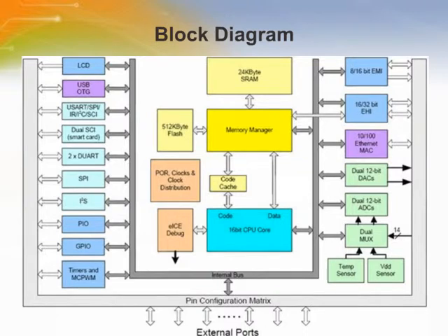Here is the block diagram of the eCOG1X microcontroller. The eCOG1X flash-based microcontroller contains a 16-bit RISC processor with powerful mathematical instructions. There are 512 kilobytes, which is 256K by 16-bit data words, of embedded flash memory, and 24 kilobytes, which is 12K by 16 bits, of internal RAM available on chip, which can be used for both code and data storage. The internal memory manager maps both internal and external physical memories into the code and data space address maps of the CPU.